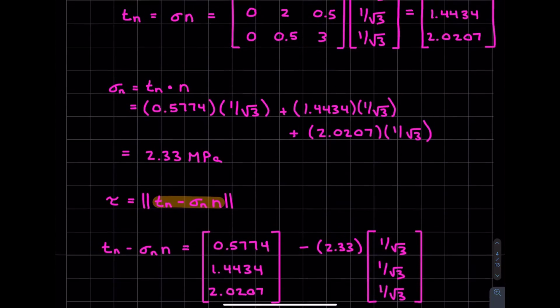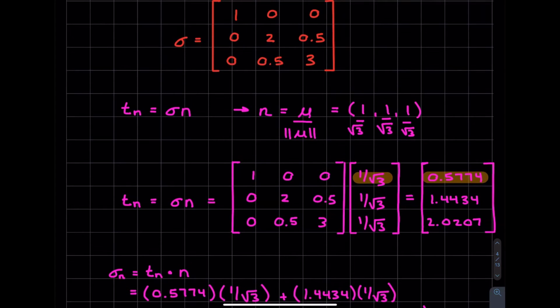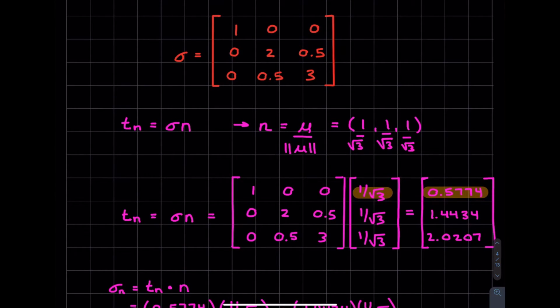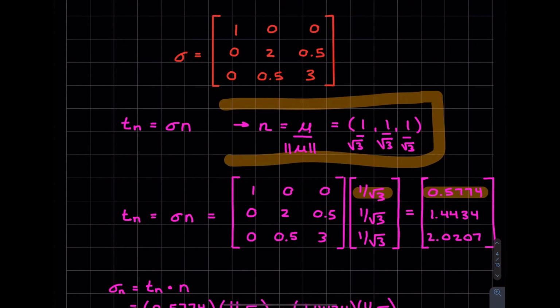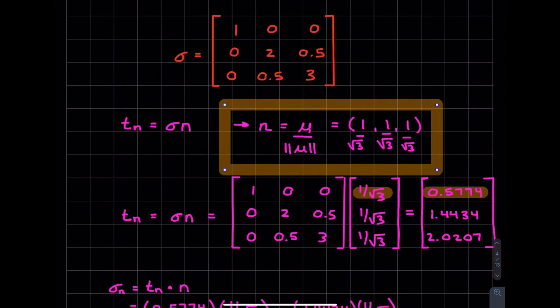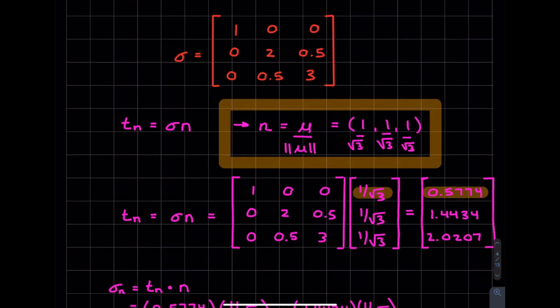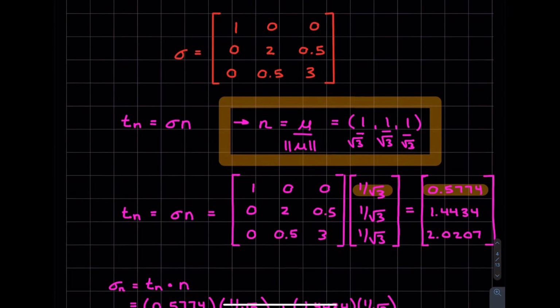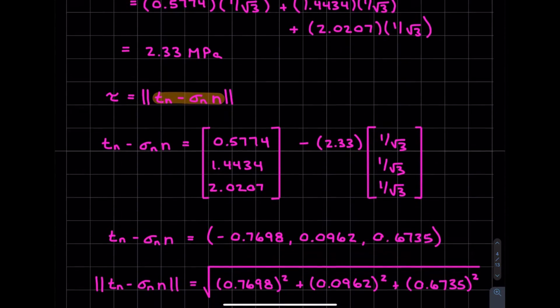So as you guys see, if we compare this to question 2, where it's basically going from 2D to 3D, the process is identical. Nothing changes in the process. The only thing is there's a bit more work because, of course, we have extra components. The only real trick to this question that I'm going to highlight for you guys is this right here. Remember that our n vector is a unit vector, so please make sure that it's normalized. If you guys go 1, 1, 1 all the way throughout, then everything will be wrong. So it's very important to know that n is normalized.